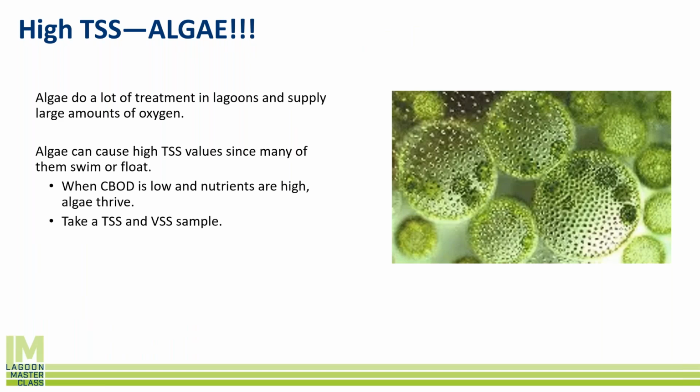If it's inorganic solids, then that probably means we're getting some sludge that's kind of carrying through the system, and so it's broken down, but it's inorganic things like salts and things along those lines that are moving their way through the system and causing high TSS.